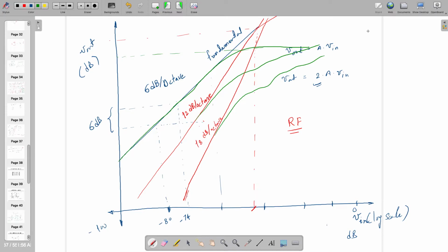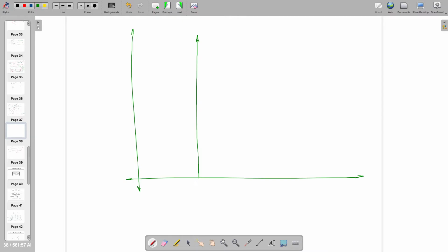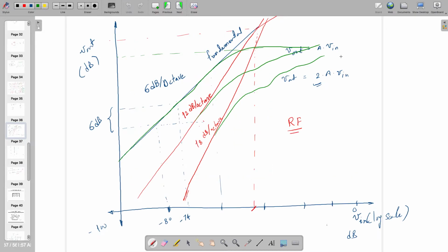But when you want to do some analysis, because you keep on increasing the voltage, let's say you have given fundamental equal to supply voltage, exactly equal to VDD, it reached. What do you think will happen to the second harmonic? It might be near to second VDD only, or the third harmonic will be just a little bit below, or maybe in the range of VDD only, right? Now if you keep on increasing input even beyond VDD, all will reach VDD someday. So that is what is happening here. You can give input, no problem, until you are not damaging your transistor.